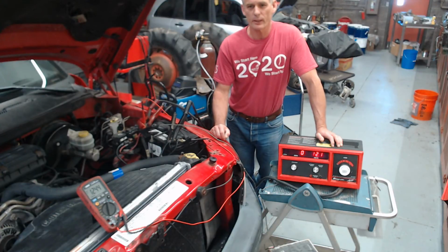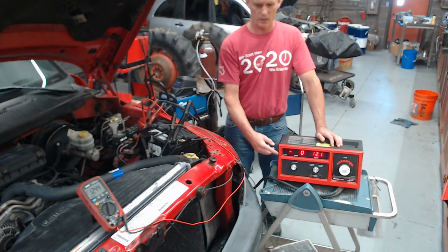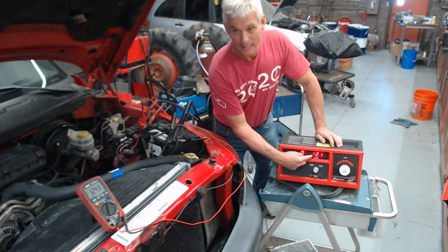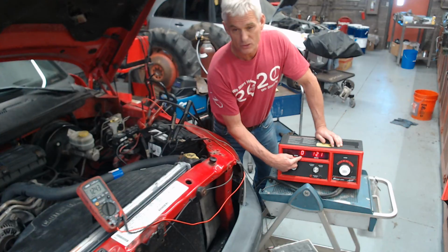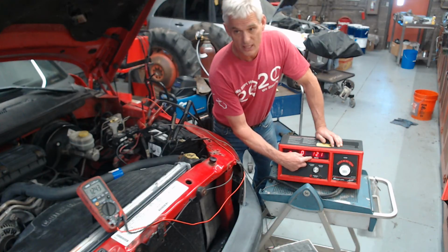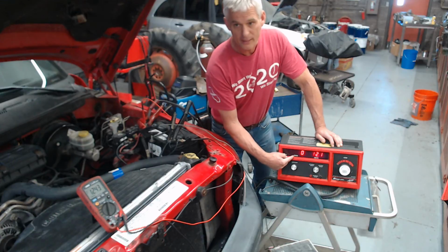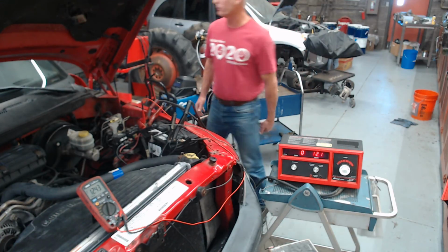So again, we're going to listen to cranking speed and so on. But what's going to happen is you're going to be seeing the amperage right here that this starter motor and starting system are going to draw, and we're looking for this voltage to stabilize. It's going to stabilize, let's say, at 10.8 volts or whatever, and we're going to read the amperage. So here we go.